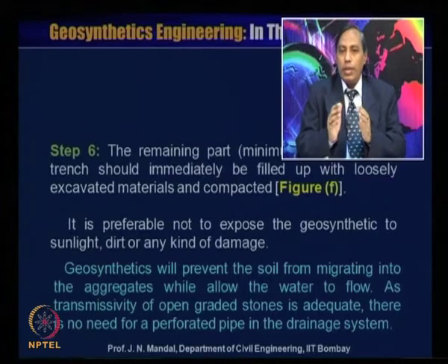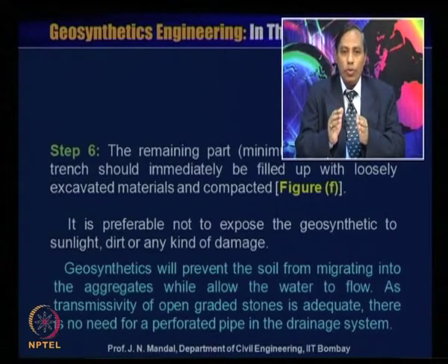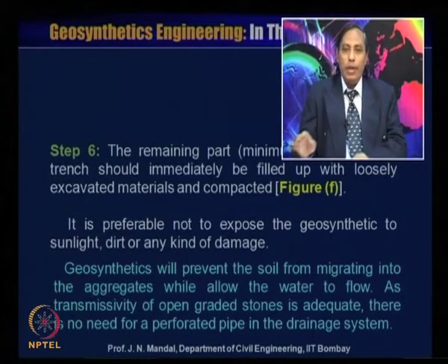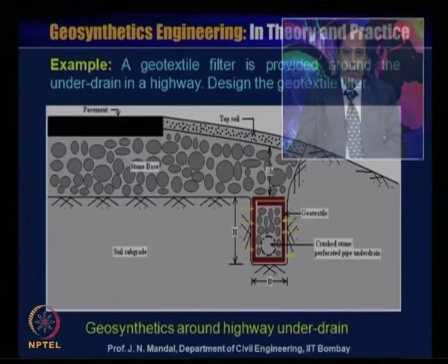Geosynthetics will prevent the soil from migrating into the aggregate while allowing the water to flow. As the transmissivity of open graded stone is adequate, there is no need for a perforated pipe in the drainage system.